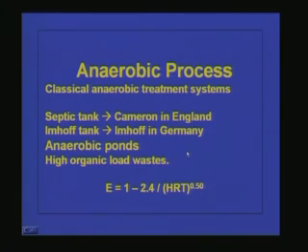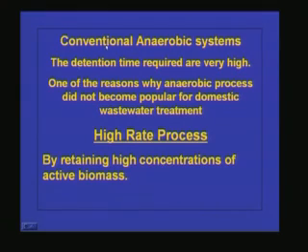So we can see that the HRT is in the range of 5 to 10 days. So the volume of the reactor required will be very high. That is one of the reasons why the anaerobic process did not become popular for domestic wastewater treatment.